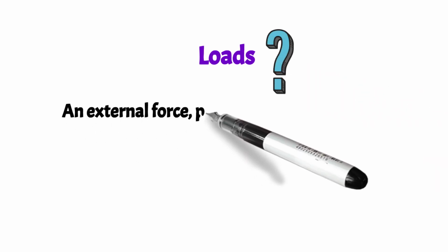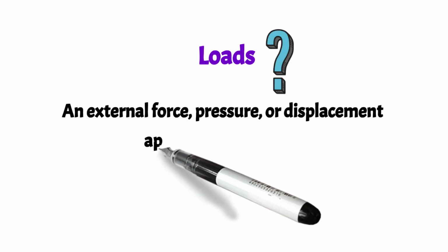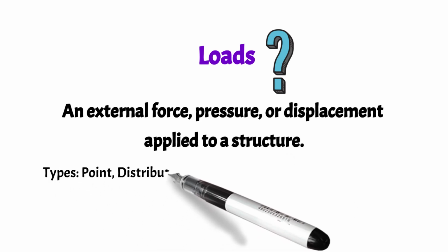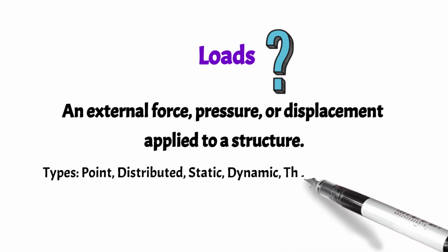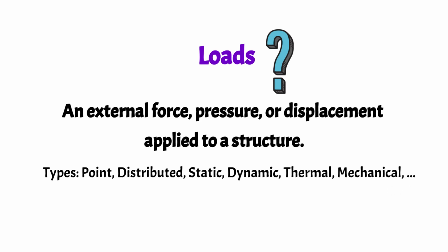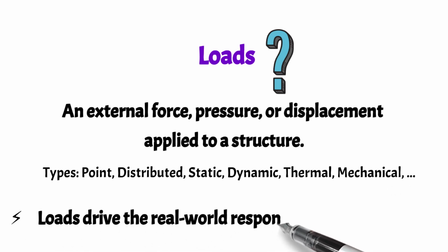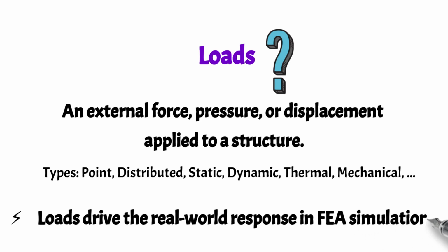The term loads in the context of finite element analysis is an external force, pressure, or displacement applied to the structure for a mechanics problem. For a thermal problem, it could be temperature or heat. Loads can be of different types. They could be point loads, distributed loads, static, dynamic loads, and it could depend on the physics as well. And they drive the real world response in finite element simulations.